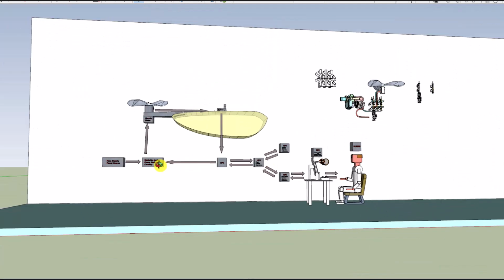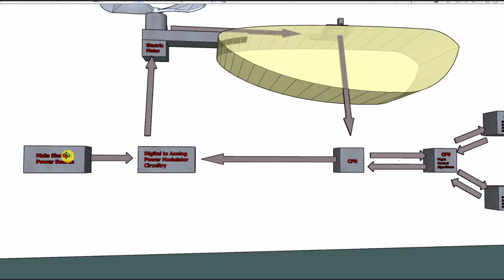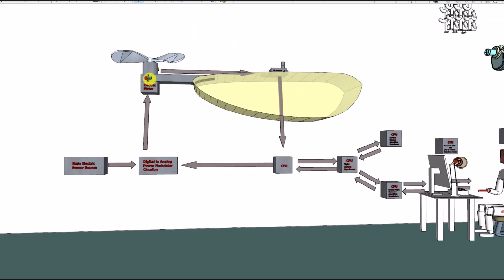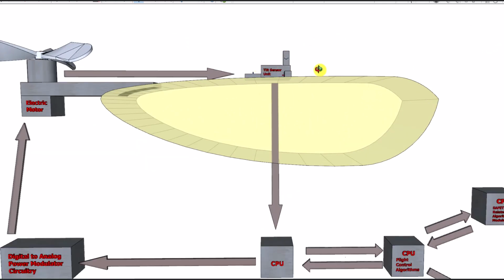The central processing unit then, here is the power to the motors. The central processing unit, on the basis of all these decisions, sends advice or commands to the motor, telling the motor how fast it wants it to spin. So instead of 1,000 RPM, it might ask it to spin at 973 RPM, and it may ask the other motor to spin at 1,002 RPM. This effect occurs, it changes the values of these sensors.